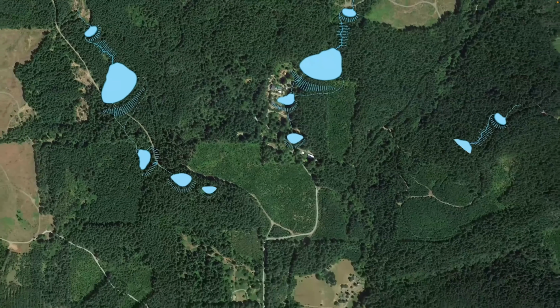The first key to a spillway is that it is not built over or even within any of the loose soil that is left from the dam construction, but instead is built around the dam into the native soil on one side or the other of the valley. The spillway is for moving flow out and around the pond when the pond is full. The height of the bottom of your spillway is going to determine your ultimate water height in your pond.